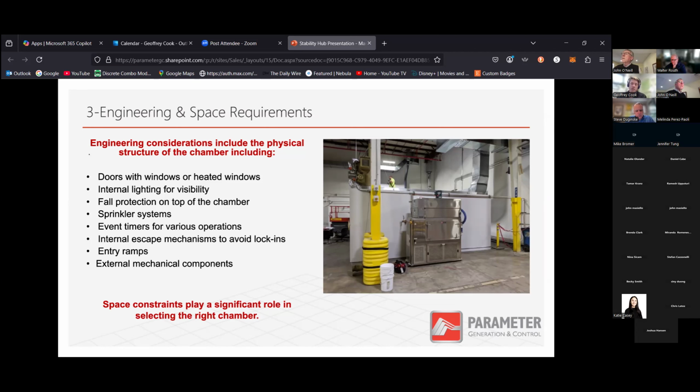Sometimes you put the unit on top of the chamber, you build an entire office space around that chamber with a drop ceiling. Utilities run all over the top of the chamber, and you can see that unit being neglected because people forget about it. It's sort of out of sight, out of mind, sitting above a drop ceiling. And unless you are very intentional about your preventative maintenance, you can have a unit go down and find that the repairs needed are much beyond what would have been needed if it had been properly maintained.